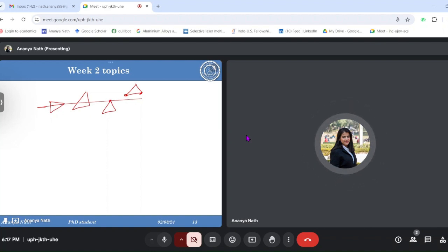So here this point is over this line, so this is my slicing plane, this is T, and in this T, these points are coming, so this triangle will be considered with these vertices and this intersecting point. This triangle will be considered with the intersecting points only. This triangle will be considered with these vertices, and this triangle will not be considered because there is no connection of this triangle with my line of slicing.